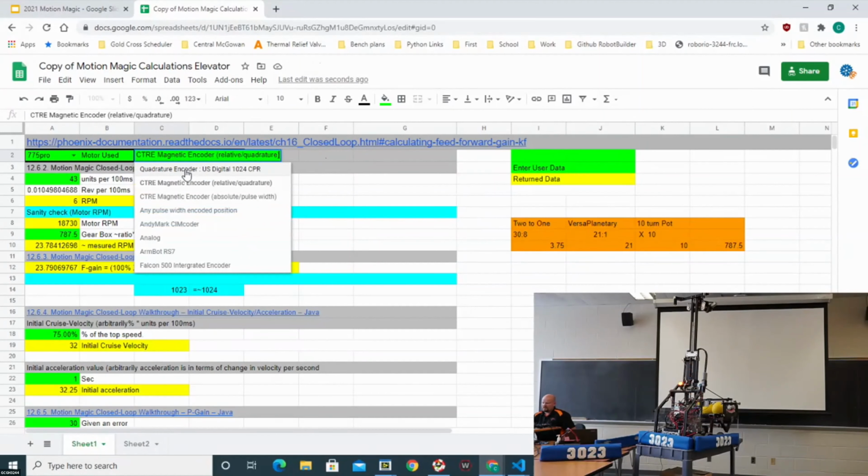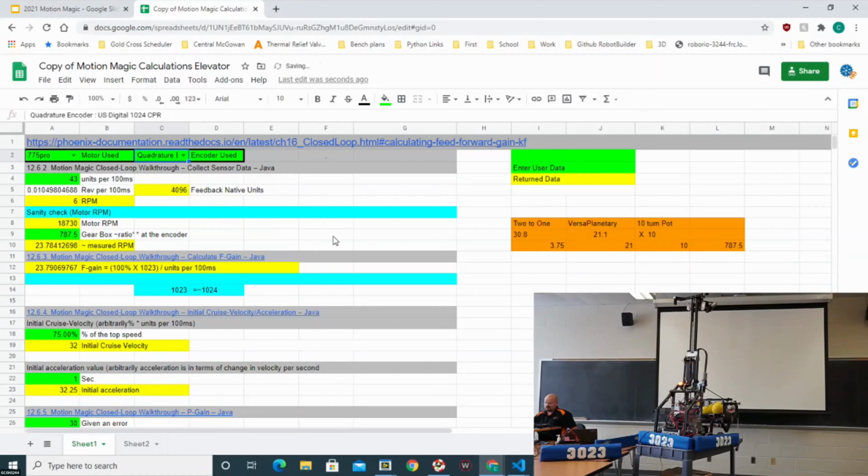In your experience, is there benefit one way or the other to where you put the encoder? We always thought, if I want it on the output shaft of the mechanism, wherever the motion is going, so that the units are something you can visually see relative to the mechanism, as opposed to at the motor, which may spin a whole bunch of times or something. Do you have any recommendations? Is it better one way or another?